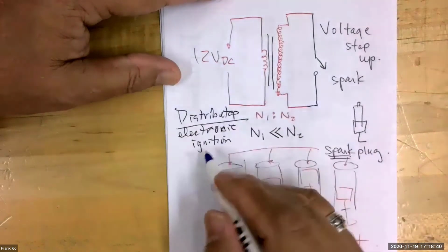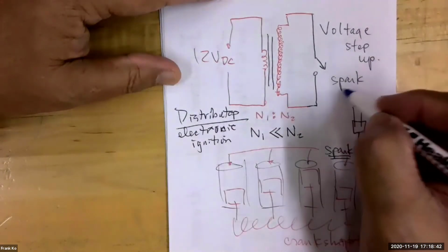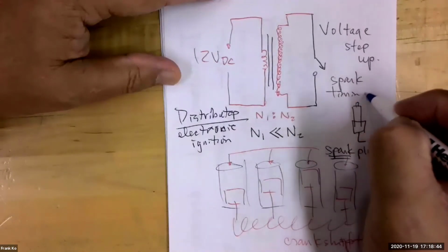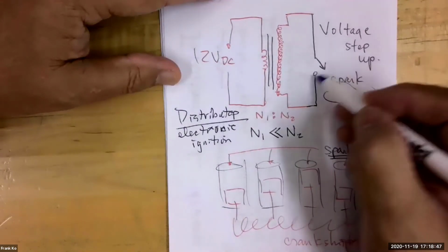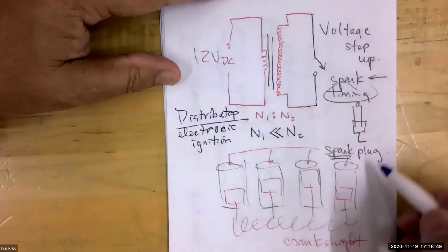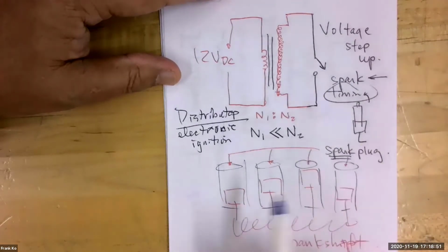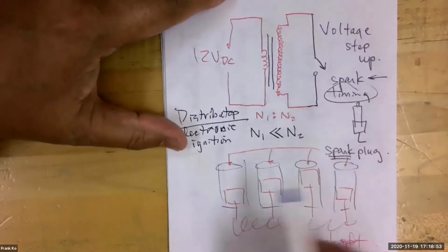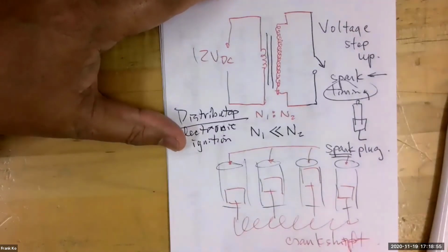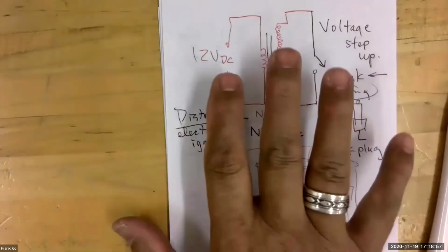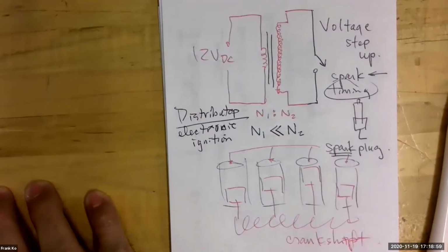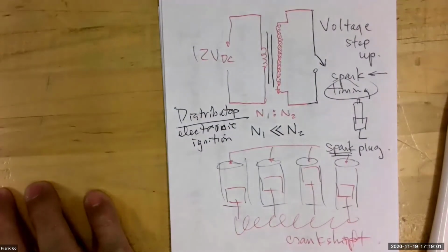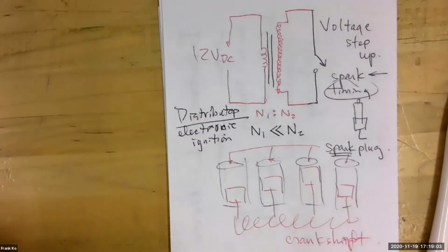Both of these guys control the timing of this switch that creates sparks at a very specific time so that each cylinder fires at a specific time to keep your engine going. Okay, that's all I'm going to say about that, because that pretty much addressed most of the answer to that question without giving you all the giblets.